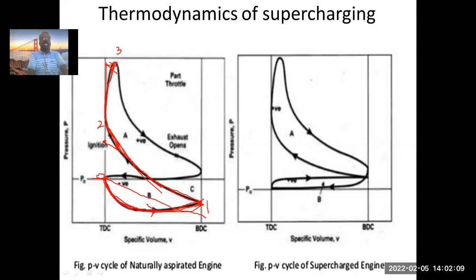Okay, and further as the piston moves, at this point your combustion is over, meaning the heat production due to burning of the fuel, whatever heat was being produced, that completed. Further, no heat is going to be produced by burning of the fuel, and as the piston now moves down, the pressure is going to reduce. So pressure reduces.